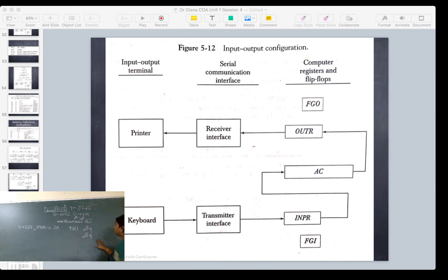The next instruction under this category has PB10. B10 indicates that the 10th bit in the instruction register is 1 and P indicates D7IT3. The instruction is OUT. OUT means I am going to send some data to the output device. So the data will be available in the accumulator. It should be sent to the output register, and the output register is always ready to receive data.